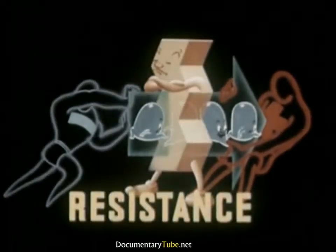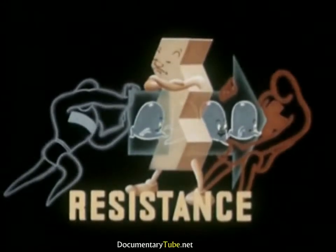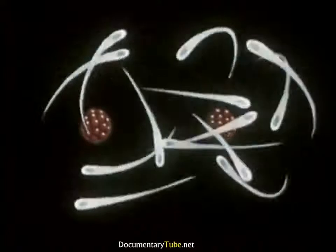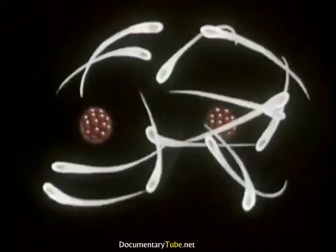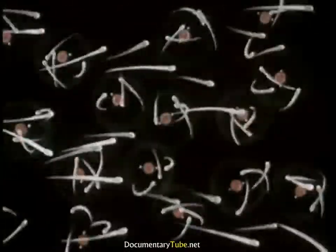And now the third factor, resistance. This factor is controlled by the nature of the material through which the electrons flow. Again, going back to the motion of electrons in a metal, we said that they moved freely about and among the atoms. However, even in the best of conductors, some of the electrons collide with the atoms, tending to retard the movement of the electrons. This is the cause of electric resistance.